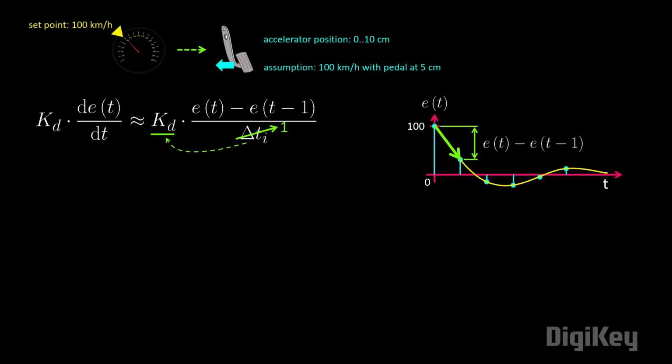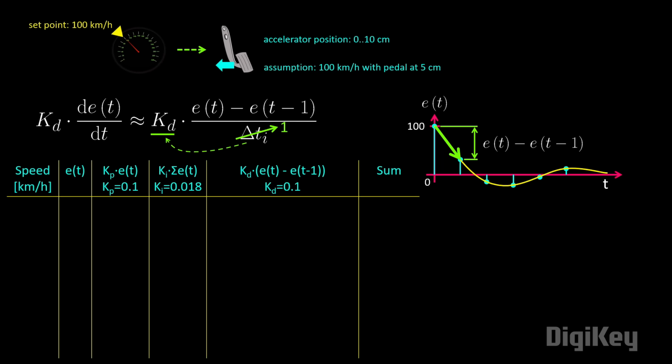The idea is that we want a term that can tell if we are approaching the goal too fast and dampen the response just enough so that we don't overshoot. So let's work on another simple example. Here we've added the proportional, integral, and derivative terms. I've adjusted the Ki coefficient to be a little higher. That way our speed increases much more quickly toward our goal, at least in theory. It's not a perfect example, but it should illustrate how the P, I, and D terms work together.